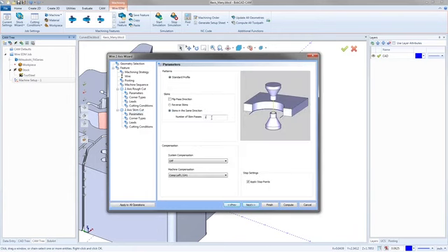On this page here, I can actually tell BobCAD how many skim passes I want. So I usually wait until I get to the final cutting conditions page of the entire toolpath before I even start setting up the parts. Because if I do multiple skim passes, in this case I'm only doing one, but in a minute we'll do 3 skim passes. If I'm doing more than one, I want to wait until I get past this page so that I know that I have 3 skim passes.